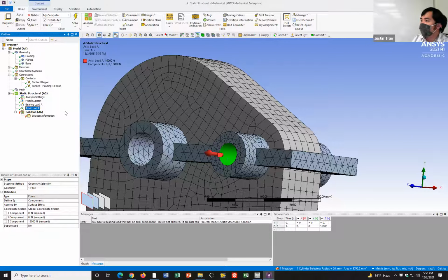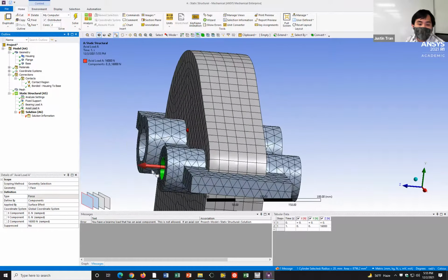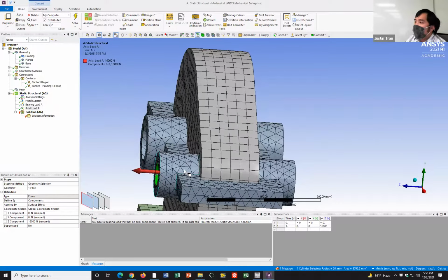So we're saying the shaft is creating an axial force opposite to where it's connected to. Yeah. So basically the shaft is inside and it's being pulled out. And the fact that it's being pulled out will create an axial load on that hole. Yeah. All right. And so go ahead and apply the rest of the loads onto the holes.